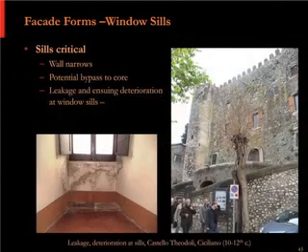And that's Pecorino, a low durability stone. The photo in the middle is actually the same building as at the right, but on a courtyard side where they have travertine windows. And there they've put sloped mortar topping on to try to get that water off the top of the windows. So both are different types of retrofits to try to improve the defect in the original design, which was that the tops of those windows were basically flat.